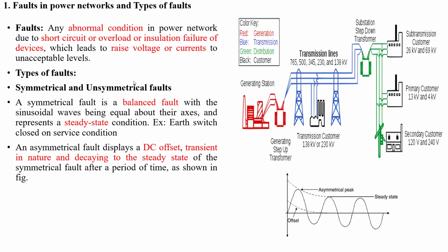If the current crosses more than 50 kA and lasts more than 1 second, the equipment cannot withstand it, so before that we should interrupt the circuit. How we interrupt it depends purely on the protection and control devices used in substations.